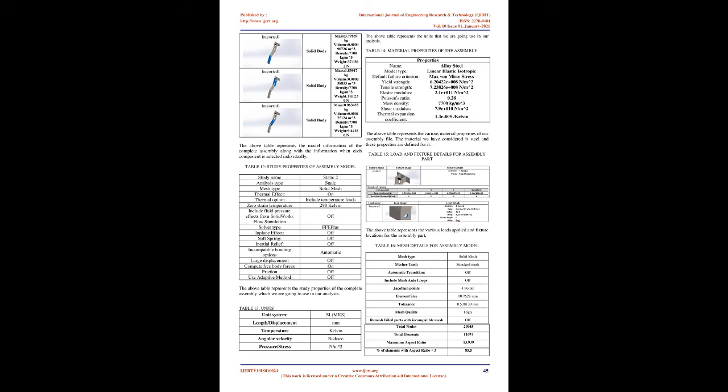7. Click on the motor icon to open the motor dialog. Under motor type, select rotary motor. 8. Under component/direction, select the cylindrical face of LINK2 pin to the bottom, see the figure, for both the motor direction and motor location fields. The motor will be located at the center of the selected cylindrical face.